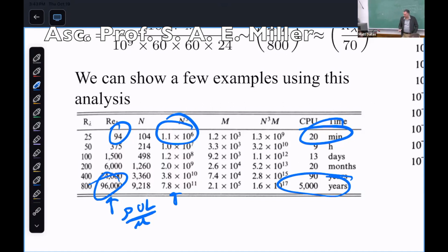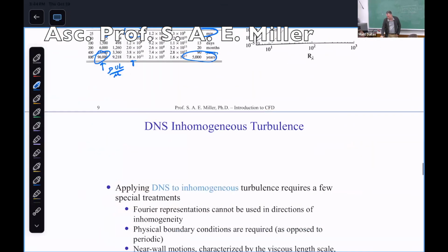5,000 years. Now, what is the Reynolds number of an aircraft we flew on? It's huge. It's tens of millions. So we can only resolve about 100,000 when we need a Reynolds number of tens of millions. And this is not scaling linearly, obviously. So if you look at a DNS, a simulation, just of discretizing an airflow of an airplane, which isn't even that fast, you would have to take all the computer power we've ever had over the entire history of humanity to simulate it. And you still wouldn't have enough computer power. So we hope that something like quantum mechanics and magic will come along to give us the power. Then we say, well, there's turbulence modeling, which is a whole other story.